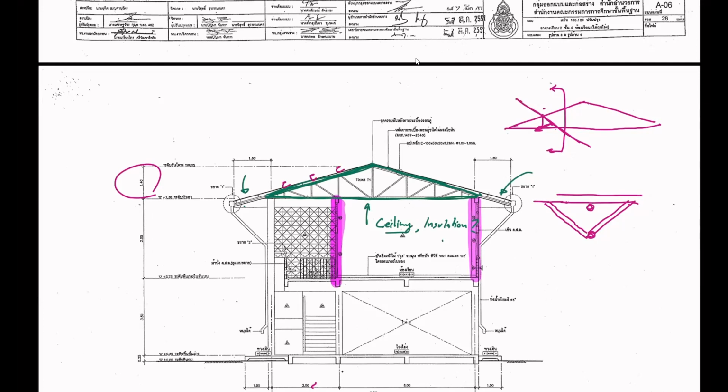And you have here and here. You need to have two on top, otherwise you cannot install the roof because of the change in slope. This is what we do for design. But what they do is put the purlins somewhere on the top chord. But the structure survives simply because, first, where is the load on the roof? What is actually the live load on the roof? I should say live load too.